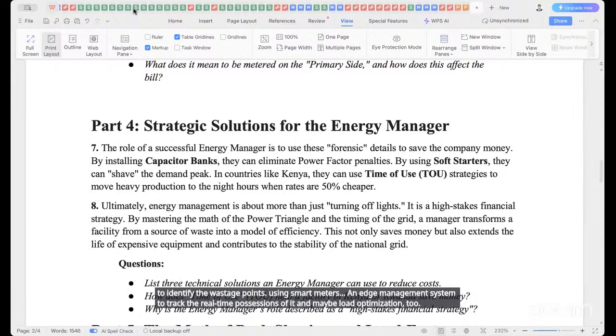You can use load optimization by eliminating the idle load. If you have a 3-phase transformer, make sure those phases are being utilized very well, not that one is overloaded, just to balance it up.